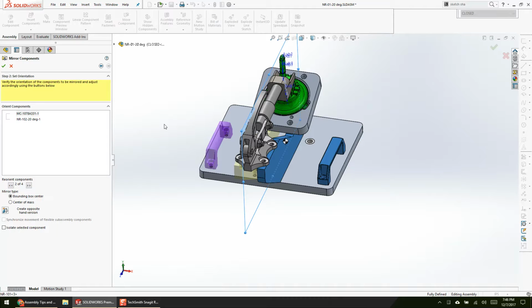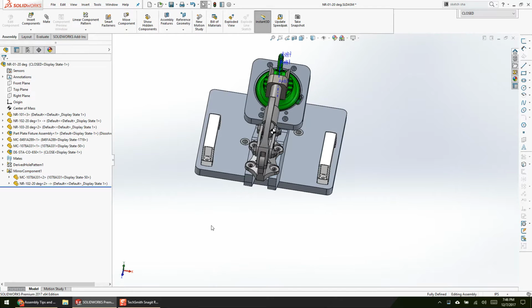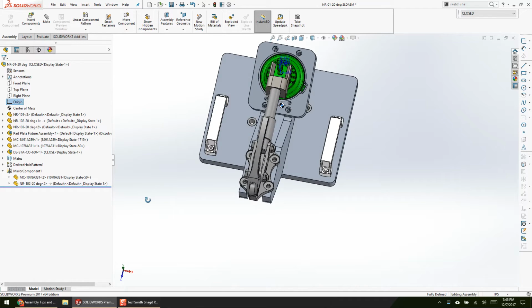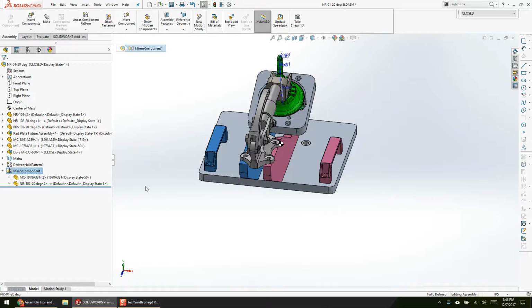It's not exactly middle in this instance. If my origin was in the bottom left-hand corner, this wouldn't work. So I can limit my liability throughout the design by having the origin in the middle and mirroring about that center plane that I got for free. I could always go and create another plane, but then I'm increasing my liability to decrease my liability.